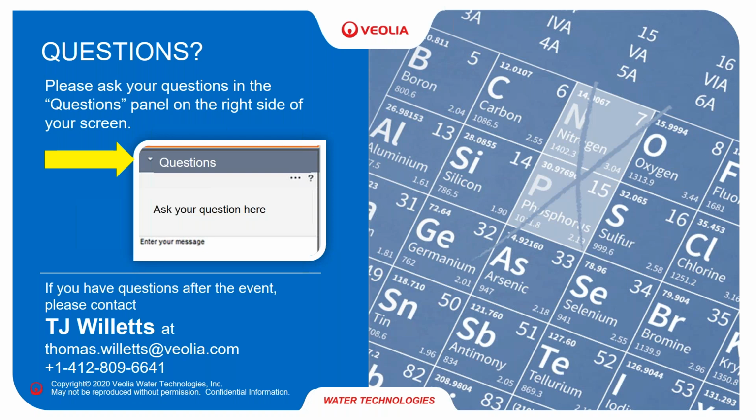Okay, another question, and it says that if we use seawater for flushing, is it easy to use biological treatment for phosphorus removal? As I mentioned in the TDS conversation, we just need to look at the concentration of salts. If it's just the seawater, it will be strongly bacteriostatic, so using biology is going to be a little bit more difficult.